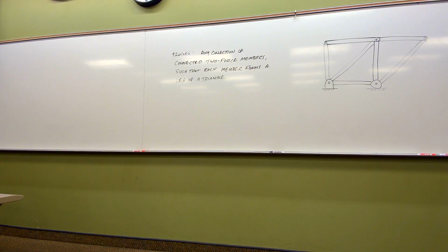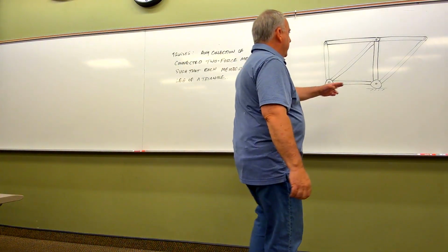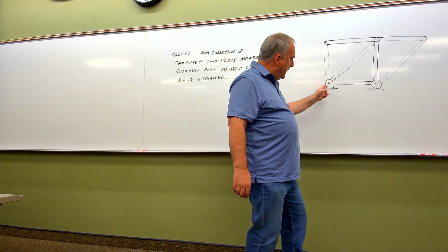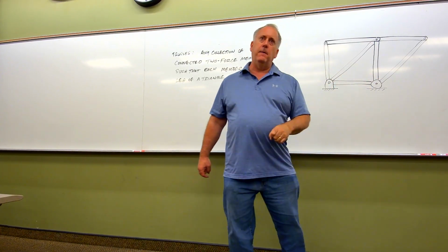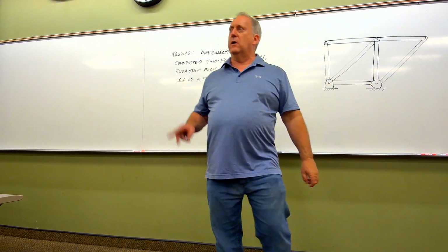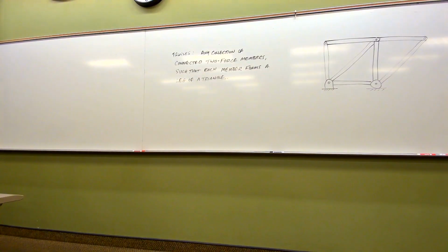Wheels, we simply show as a single normal force, right? So if you think about that free body diagram, if I did a free body diagram of just this truss right here, kept the whole thing together, and I only was interested in these connection forces, these support forces down here, I would have 2 support forces here, 1 support force here, grand total of 3 unknown forces, and what's my budget? Now everybody's going to hold up the number of fingers on this one. What's my budget for equations with 1 free body diagram? 3 equations, 3 unknowns I get to solve.